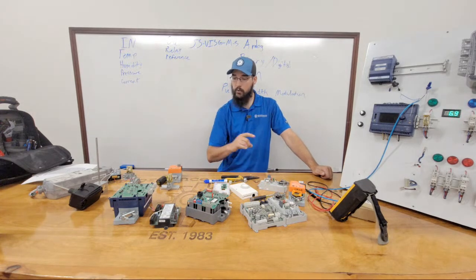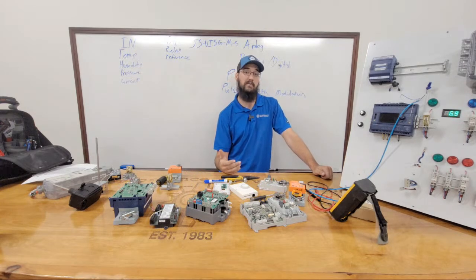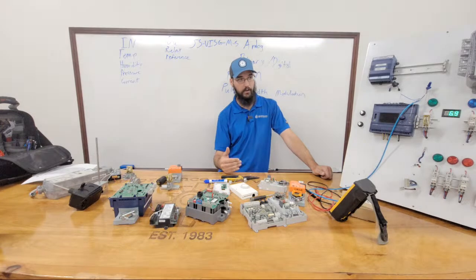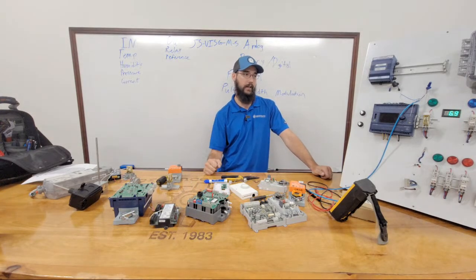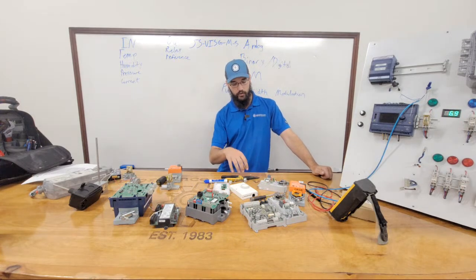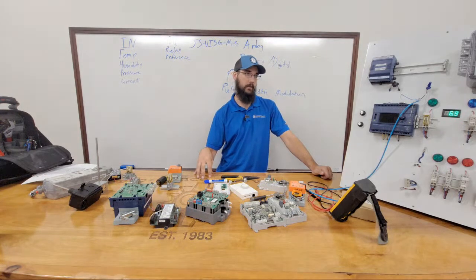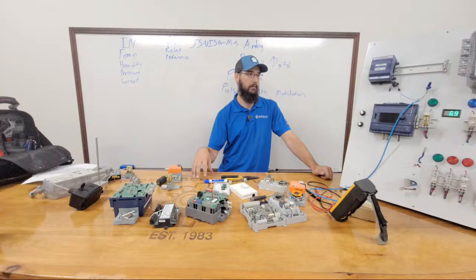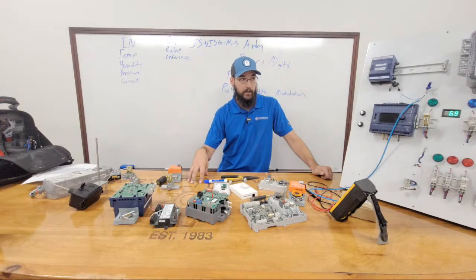The vast majority of controllers, when you power cycle them, so that means you're going to shut them down for at least 30 seconds, preferably maybe closer to 60. Let that whole control circuit de-energize. Then you're going to boot it back up. They usually will go into what is known as a sync mode, or an actuator sync, calibration sync, damper calibration, whatever. That's the easy way to do it, but not all of them actually do that.